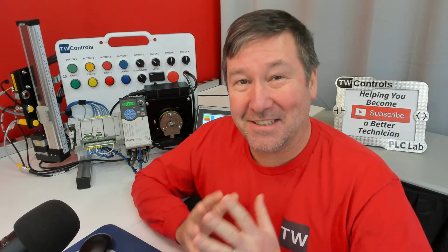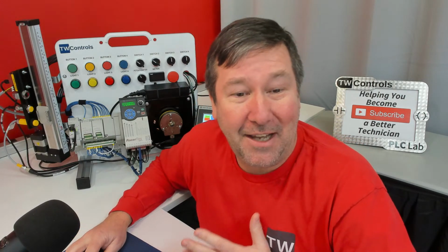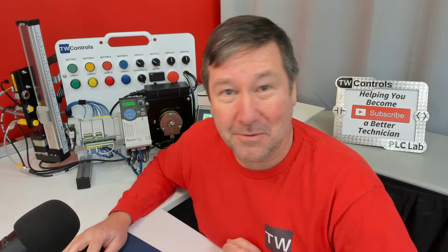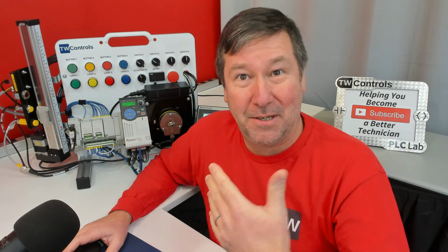This has been an interesting one in the last 24 hours. I posted that we're going to talk about trending in Ignition because it doesn't work in Rockwell Automation's Connected Components Workbench. Right after that, Randy Davis sent me an email and said they put an add-on back in, so now it does work. If you didn't know, trending was added to Connected Components Workbench version 11, and it worked fine to 21. And then in version 22, it just disappeared.